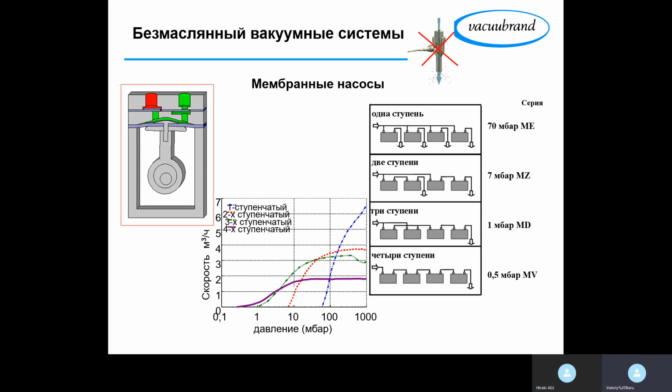So pretty much the same with a vacuum pump. If you have a leak rate in the system of, let's say, 0.1 cubic meter, is it clear? Yeah. And the pump has the performance of 0.1 cubic meter as well, then the forces will be equalized. So you are pumping out 0.1 cubic meter, but due to the leaks, you always have the same amount of air that goes inside the system.